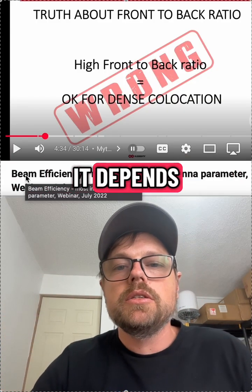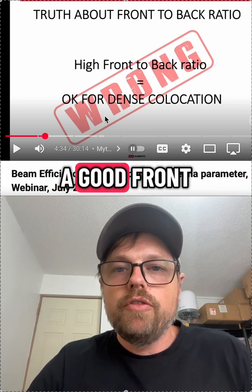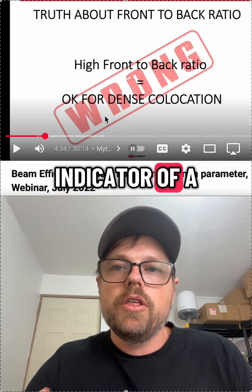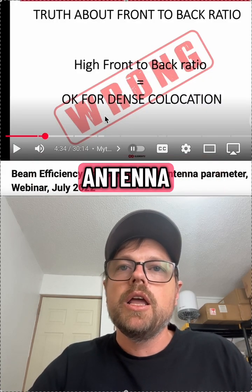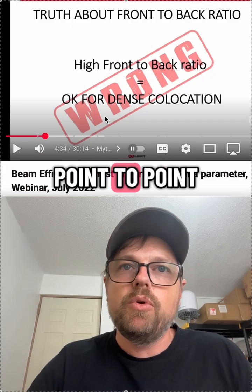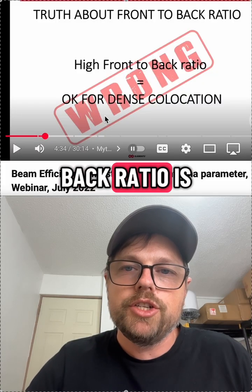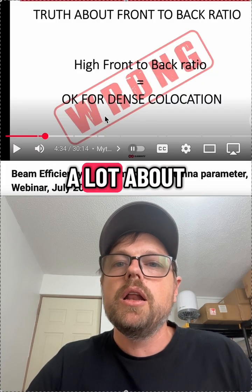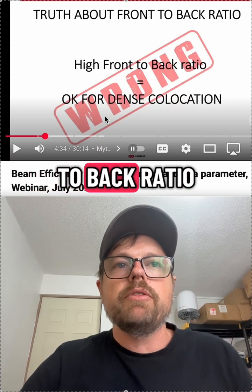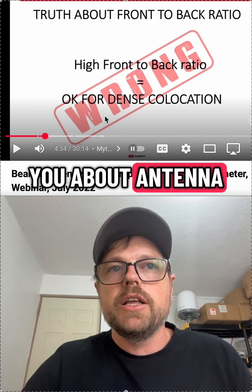It depends. But generally speaking, having a good front to back ratio is a good indicator of a high performance antenna. It is one of the best ways, particularly with point to point dish antennas. Having a high front to back ratio is going to tell you a lot about the side lobe performance, because the front to back ratio incorporates gain, which also tells you about antenna efficiency.